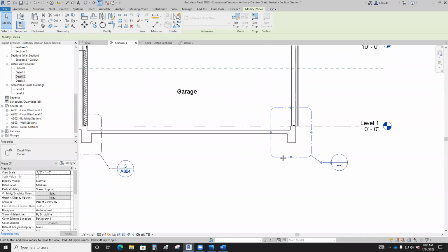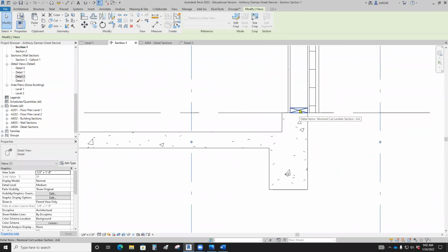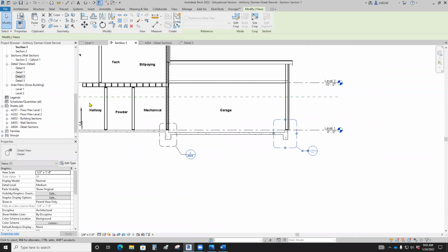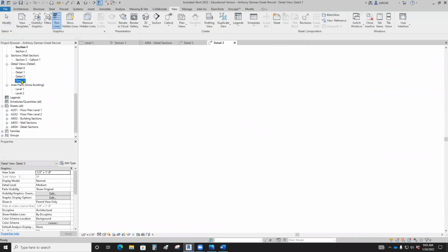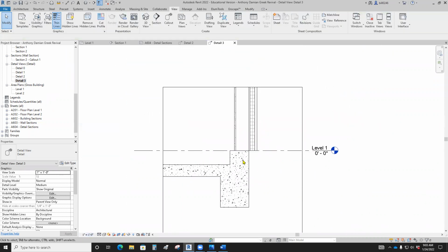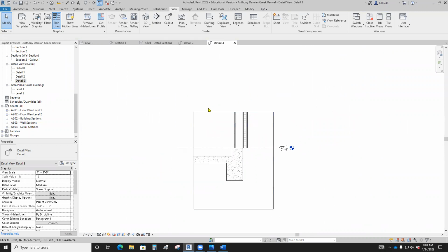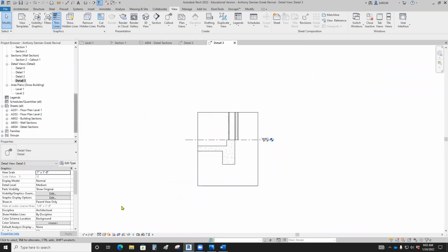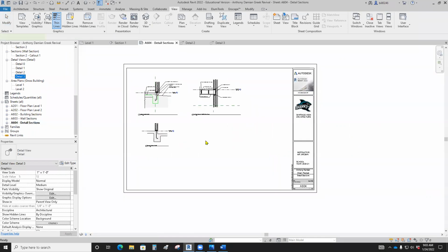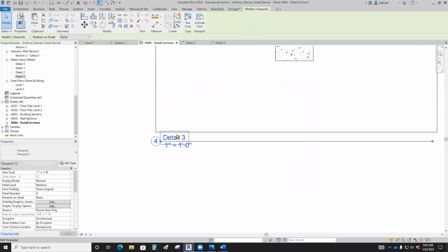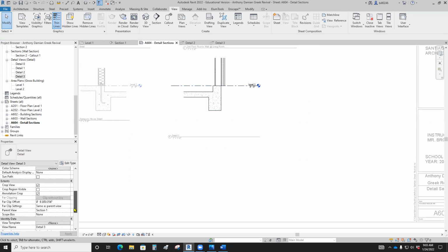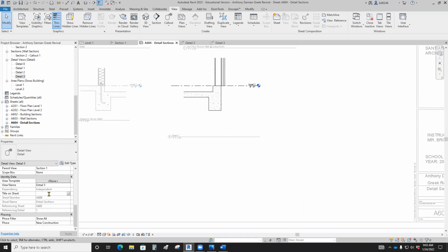So no insulation. Yes. Would this be a treated sill plate? Absolutely, because it's touching the concrete. Let's see. So let's go ahead and set that up. So this is going to be 1 inch a foot. I could have probably copied and pasted that 2x in there, and then that is going to go on the sheet. Again, I'm just going to get this kind of set up the way I want it. Now, if it says nothing on the bottom like that, that's not acceptable. I need information on that thing. You're going to do it by title on sheet. Let's see, what is that? The garage curb?